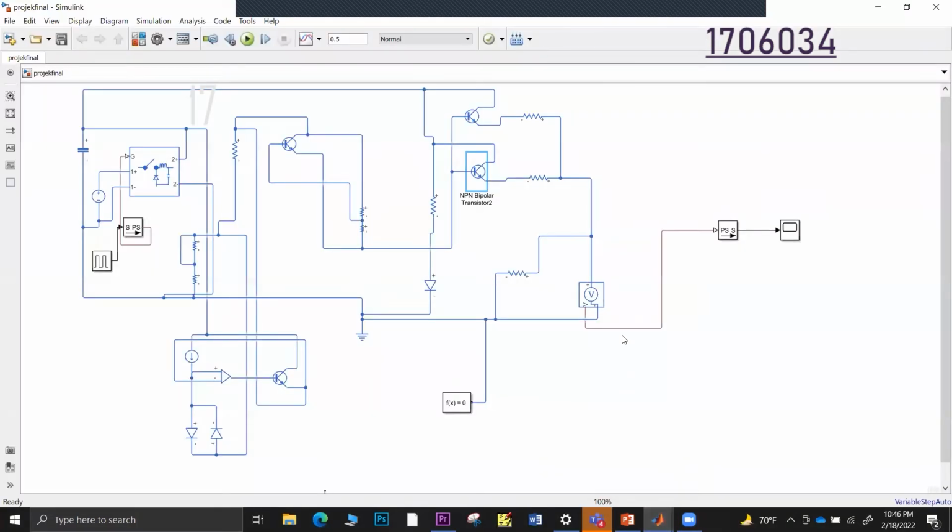The main power line comes from the mains and goes through a transformer and a rectifier circuit to produce a DC voltage of 24 volt, which we simplify in MATLAB using a DC source of 24 volt. The source goes to a buck circuitry which can control the DC output value. Then we take it to the voltage control segment of our circuit as shown here. This is a type of voltage regulator. And finally, it connects to a potentiometer circuitry which can be used to control the regulator.